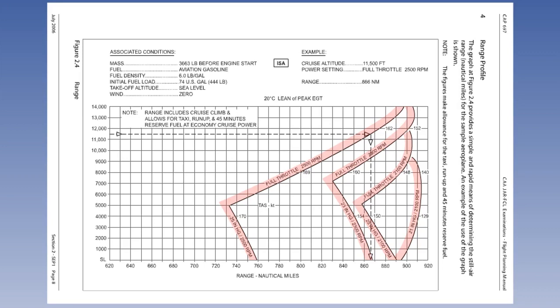Various power settings, as shown on the graph, will allow the aircraft to fly for a certain maximum range, whilst keeping intact its fuel reserves. The range figures are given in nautical air miles, called still air range, which means that the figures have no wind component. These figures will need to be adjusted for wind in order to get nautical ground miles.